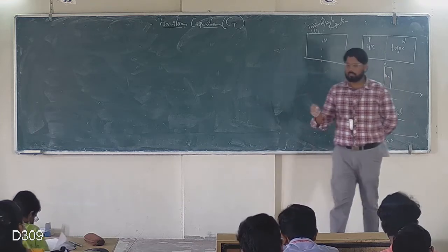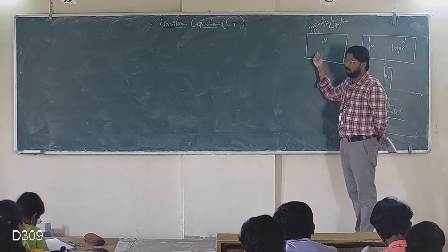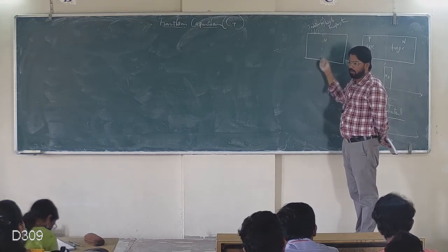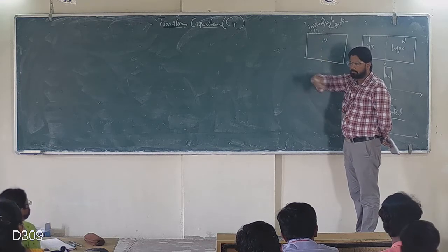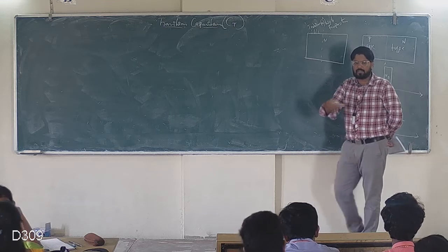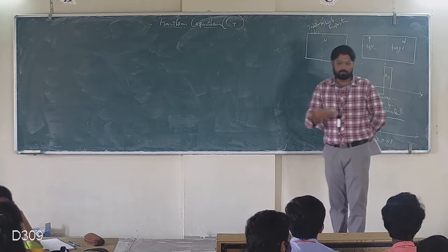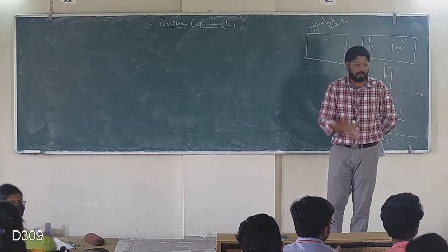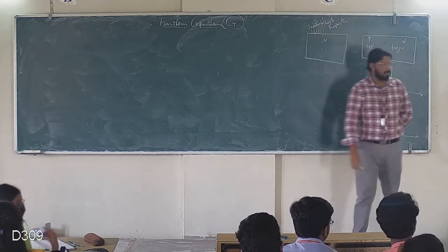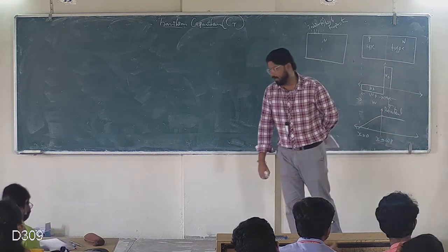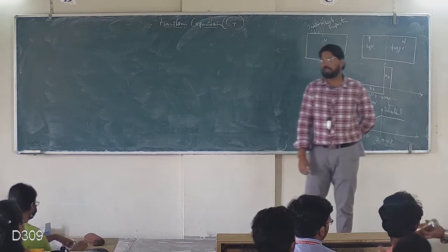I'll repeat. I took the bar, an N-type semiconductor. In that, I spread diffusion particles, indium, which is a trivalent element. After spreading, I applied a higher temperature, normally greater than the melting point of indium.